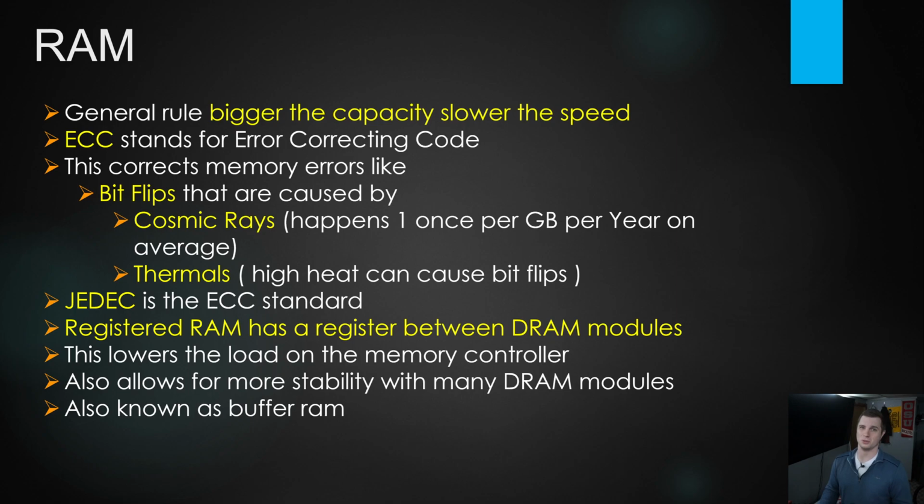And then thermals is a big one. The higher the heat, the more bit flips you're going to have. And unfortunately, I don't have a formula for you, but I'm sure there's a white paper out there if you wanted to go find it. JEDEC controls the ECC standard and most of the RAM standard actually, but JEDEC in general controls your RAM.